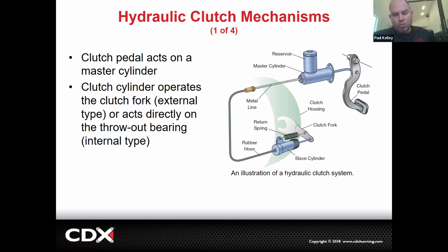Make sense? Hydraulic issue? No. Rusted out firewall. Cool. That's been an ASE concept. Okay, I'll give you another one. This push rod is adjusted too short, and this pedal has 3 inches of play right here. The first 3 inches are play. The next 3 inches actually move it, so you only get about a 1/2 inch of actual stroke in the clutch master. That becomes only a 1/2 inch of stroke in the clutch slave. That becomes, again, dragging, hard shifts, dragging you in the intersection, grinding going into reverse, and probably first too.